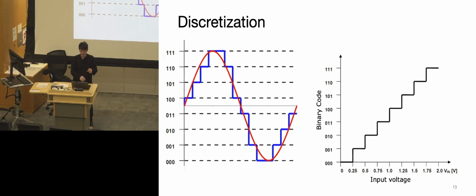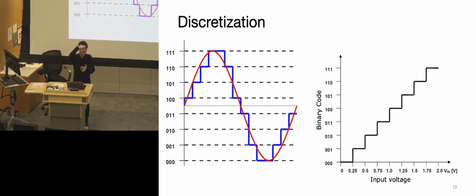Say if we have a 10-bit system, then from peak to peak voltage you have roughly 1,000 little steps, which will look reasonably smooth. If you have 12-bit, which is also quite common, then you have 4,000, give or take.